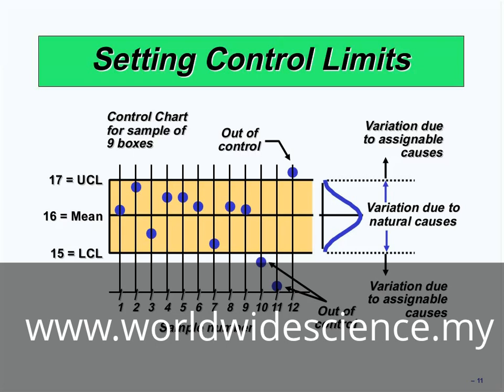The operation manager selects 9 cups of the flake and takes them to the laboratory, measures them on the scale and writes down the result, because we want to see whether the process is under control or not under control. This is the method of the X bar chart.